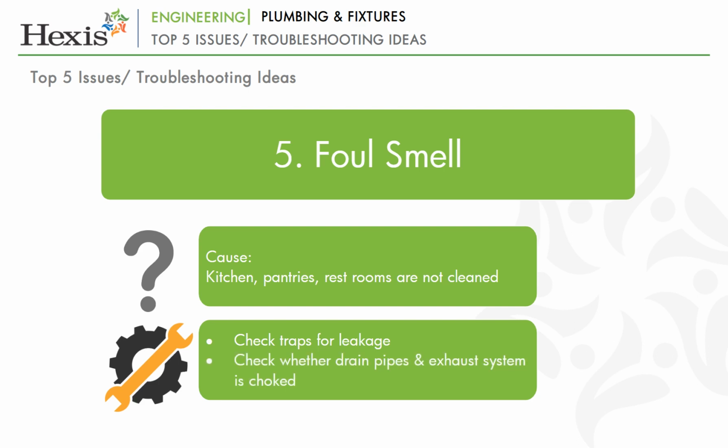Check the drain pipes for clogs since the clog itself may become smelly after some time. Check the exhaust system. A non-functional exhaust may lead to foul smell being trapped in the restroom and in some cases also spread the smell to other parts of the facility.